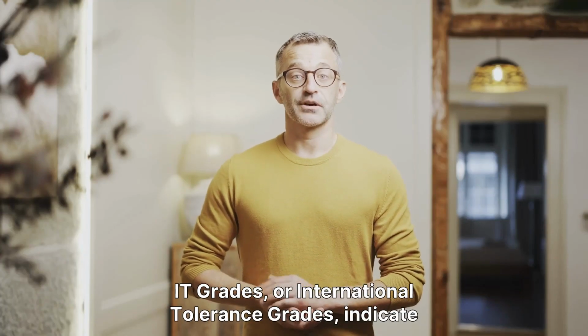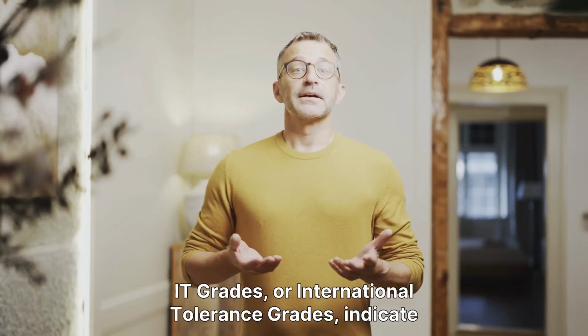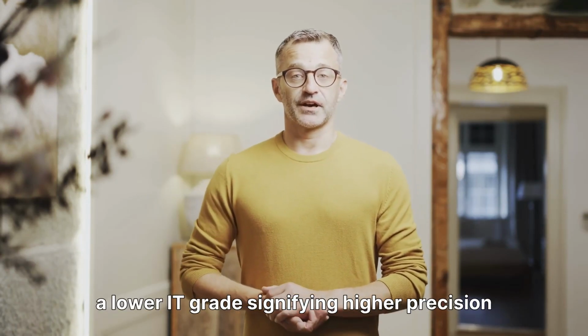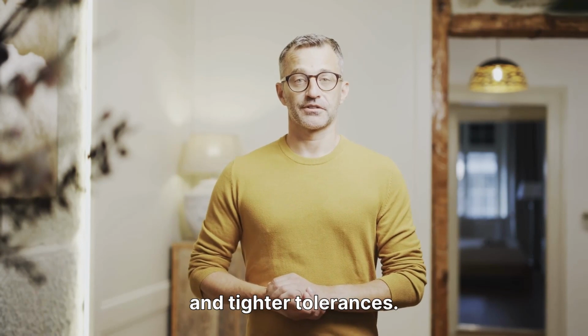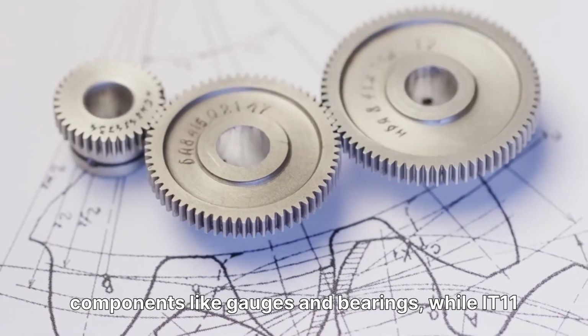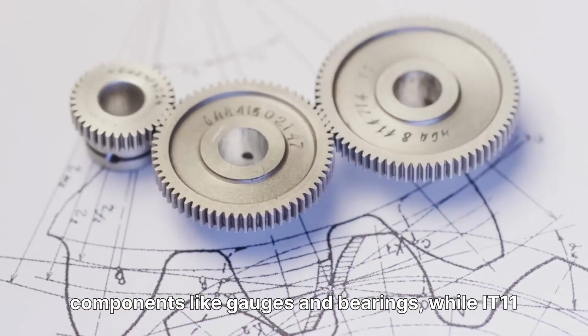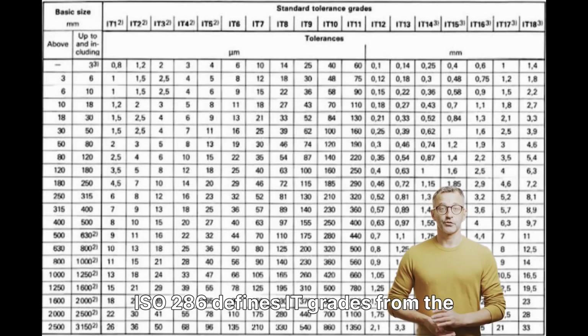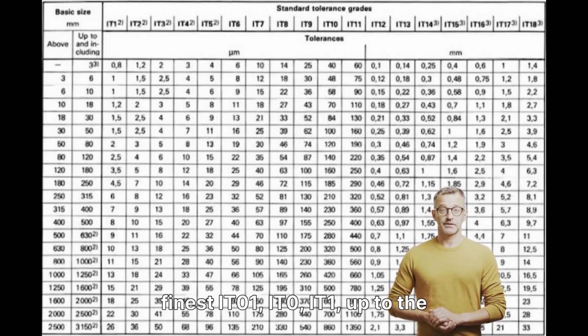IT grades, or international tolerance grades, indicate the size of the tolerance zone, with a lower IT grade signifying higher precision and tighter tolerances. For example, IT5 is for high-precision components like gauges and bearings, while IT11 is for low-precision structural parts like frames. ISO 286 defines IT grades from the finest IT01, IT0, IT1, up to the coarsest IT16.